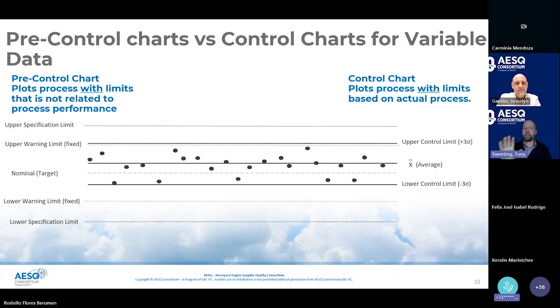Control limits are something different entirely. They tell you something else. They tell you about the process itself. Going back to the manufacturing side, it tells you this is what we manufactured previously. I'm making limits based on where I think your process sits and the width of that process as well. So the spread and where it sits, that's what it's telling you.